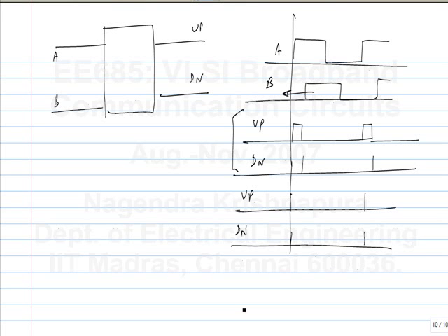So two things you have to think about are, in the ideal case, this is true, that there is no reference feed through in a type 2 PLL. Not only did we increase the lock range and made arrangements to suppress reference feed through, we made the error input itself 0. But this is with an ideal instantaneous reset. So there are two things to consider. One is reset path delay.